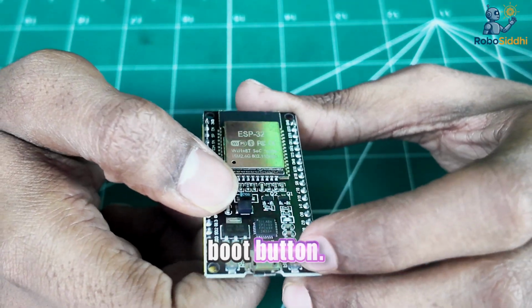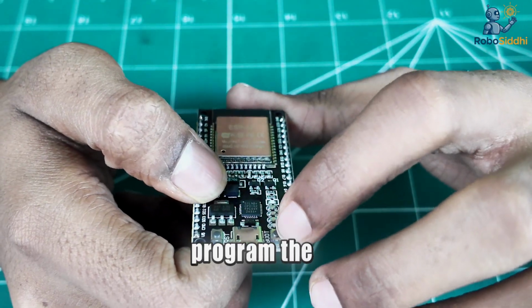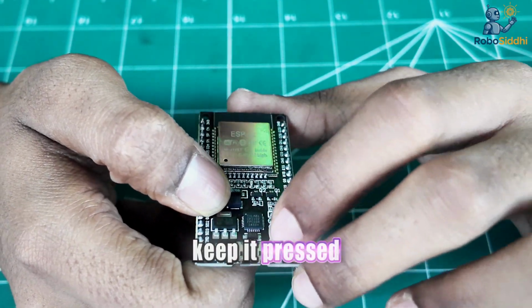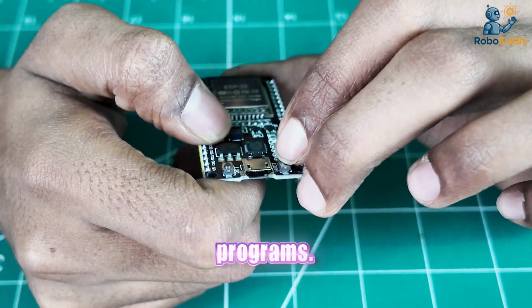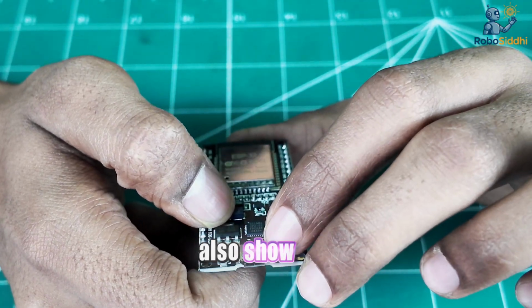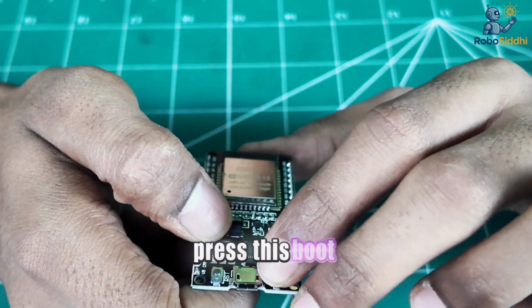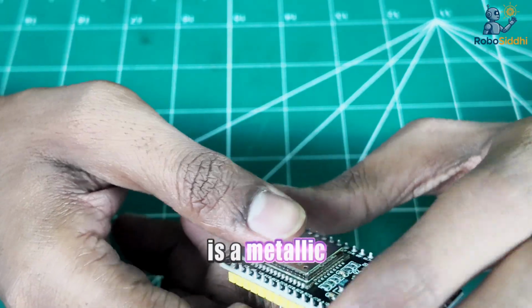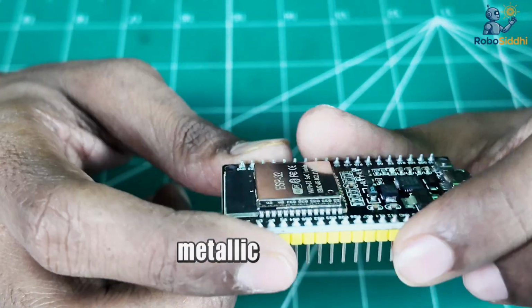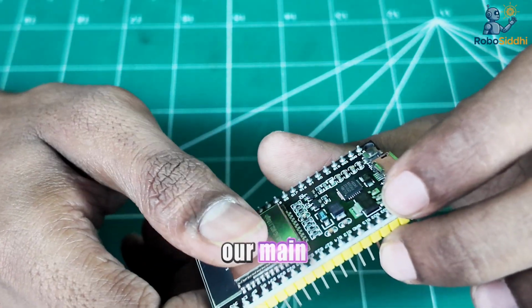Then we have the boot button. So this one is called the boot button, and whenever you are going to program the ESP32, you have to keep it pressed while the board is uploading programs. So that's when we have to use it. I will also show you whenever we are going to upload any kind of programs, we have to press this boot button. After that, you can see there is a metallic box here. This is the main microcontroller of our board.